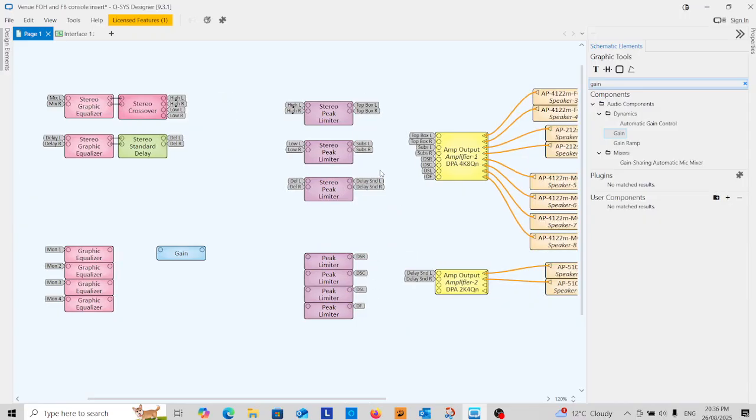So everything downrange of the peak limiters is going to be protected by them, and that's really one of the major points of a speaker management system: to protect the speakers and the amplifiers from damage from over-enthusiastic audio reproduction, is how I like to term it. This can be simple mistakes, like someone pointing a microphone at a speaker at the wrong moment. And if you're dealing with school-age children of primary or even high school, this is not uncommon. So we're going to protect our system with the peak limiters from that. So everything needs to happen before the peak limiters as the last point in the chart. I just wanted to make an emphasis of that.